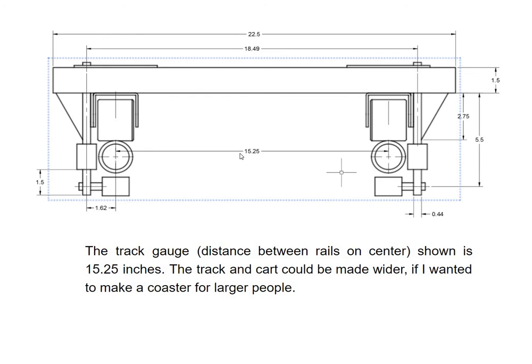So you can see that there's an 1/8 inch gap between the track and the side wheel on either side, so 1/4 inch total, and then a 1/4 inch gap between the track tube and the upstop wheel. That's probably good enough so that it'll slide and won't bind up, unless you really make your track poorly, and then you'll need bigger gaps.